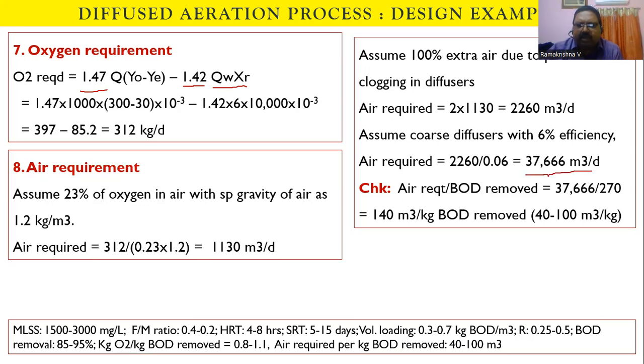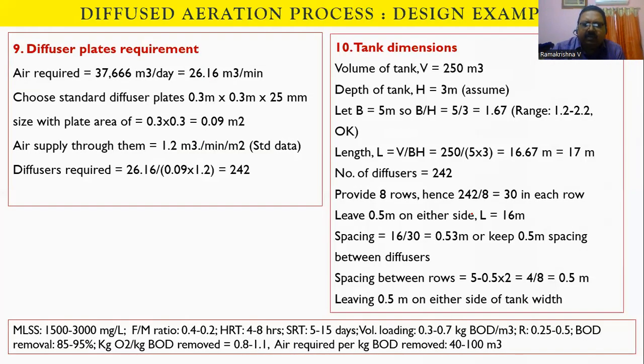So air requirement also we can check with respect to BOD removed. So usually it should be not more than 100, slightly higher, doesn't matter. Too much loading will create a problem for the bacteria. That's the only reason to look at this here.